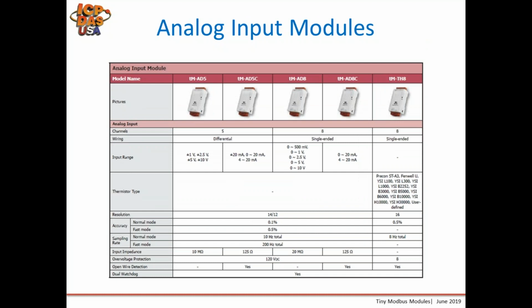This is some information on our analog input modules. Again, note different channel counts and different channel types. So you must look at your input range and match it to the table shown and number of channels. Let's see, also note 14 or 12-bit resolution.